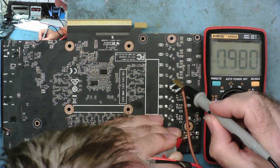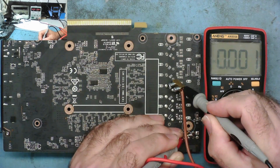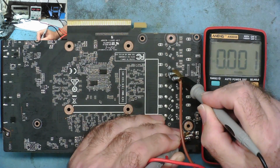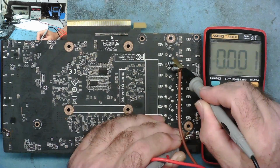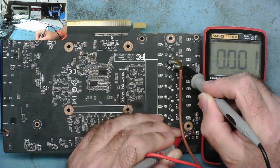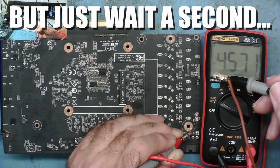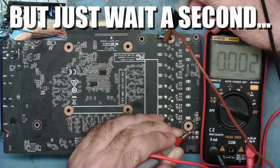So this one is giving me 0.0001. This is giving me the same. This is giving me the same. So it's basically saying this is a dead short. Does this one read any different? No. So in this case, the short circuit finder is not going to tell us which one has the short.